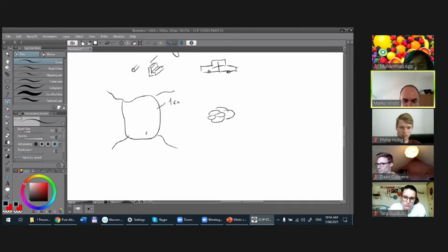Once some crack or defects appear here, it can travel throughout the crystal grain very quickly. You can just go from one side to another very quickly, and you get crack growth, right? But for some defect or crack, it's very hard to go from one crystal grain to another. It will usually hook on this boundary. So in this case, let's say the length of this crack is maybe 5 centimeters.